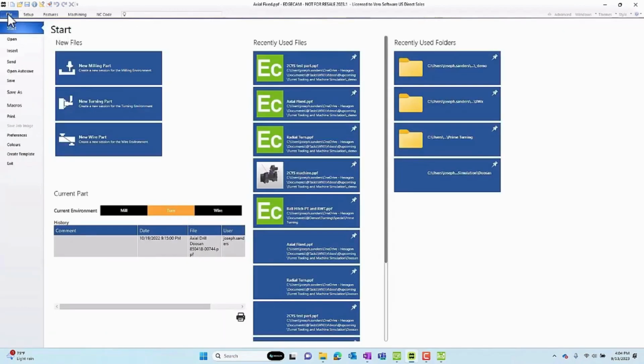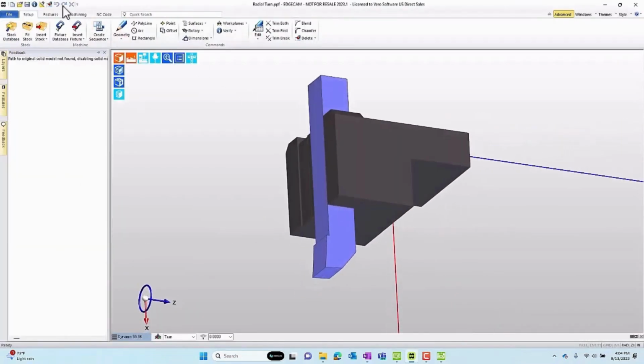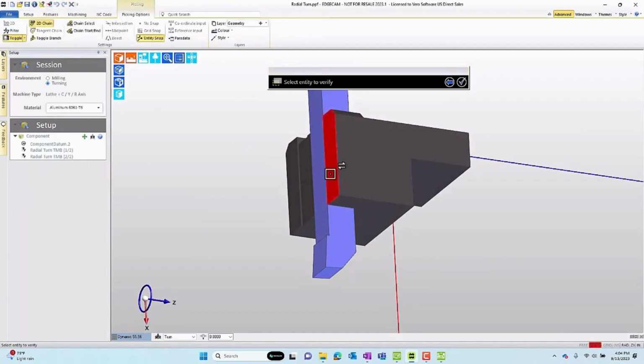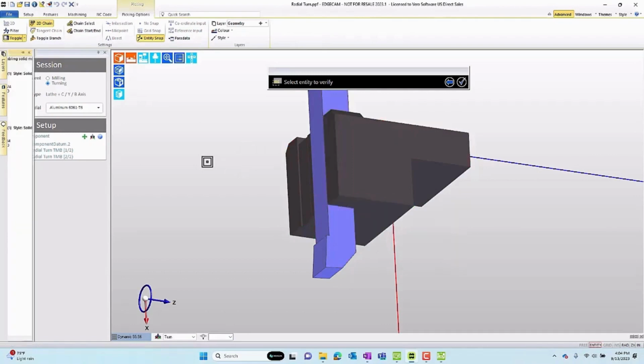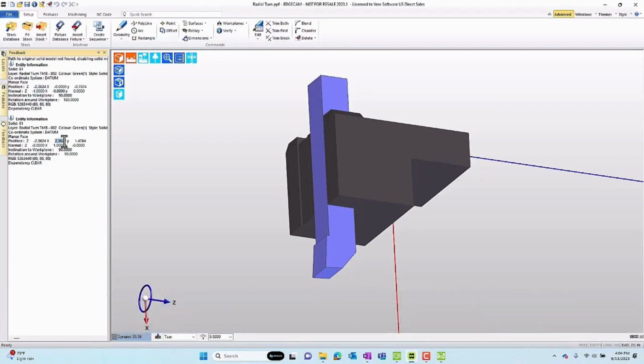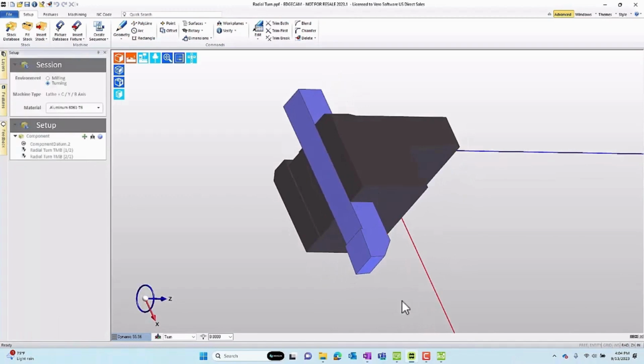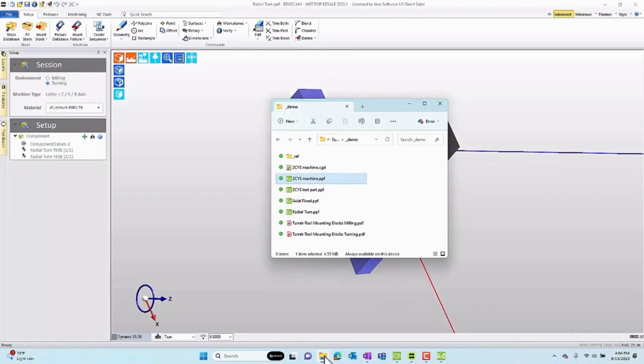And then we're going to go to the radial turn tool and grab similar information. Now this is a different block, and while we need similar information from the Z of this face and from the X of this face, the values themselves are possibly different across different blocks. So again, we'll collect this key data. Now that data is used to assist us at getting the core values for different blocks that need to be considered when trying to plan out tool stick out. Okay? How far does this tool stick off the tool setting point in CodeWizard?